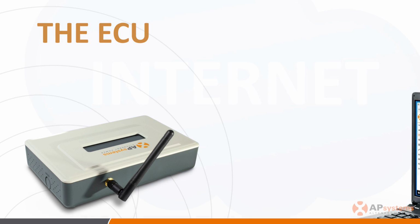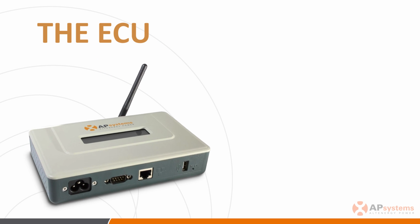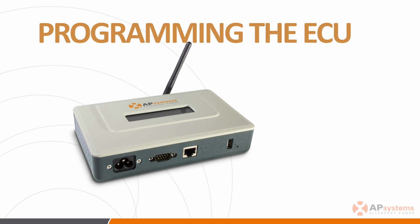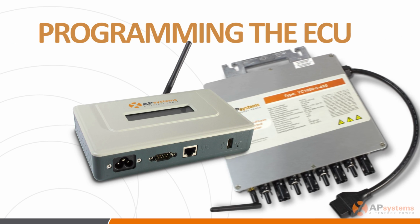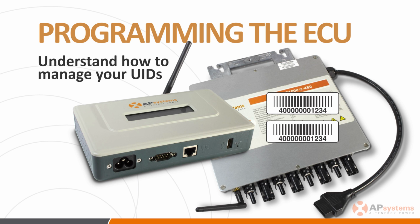It's also important to note that though the ECU communicates wirelessly with the microinverters, it does not connect wirelessly to the internet and requires an electronic bridge or direct Cat5 connection to communicate to a network router. Before jumping into the actual installation of the ECU, it's very important to understand how you're going to manage the inverter UIDs prior to the installation and registration process.